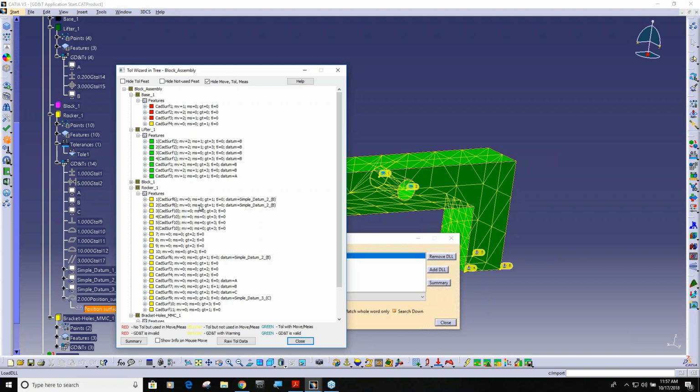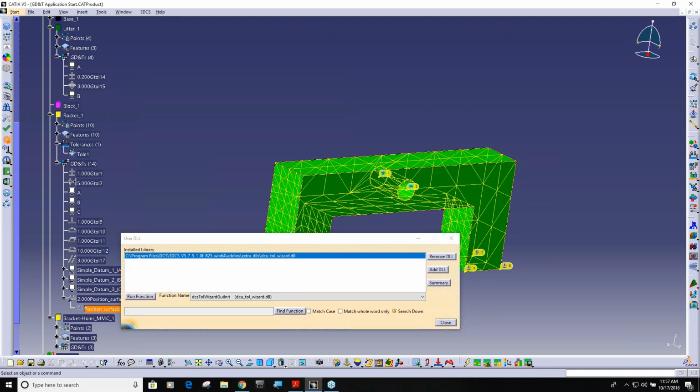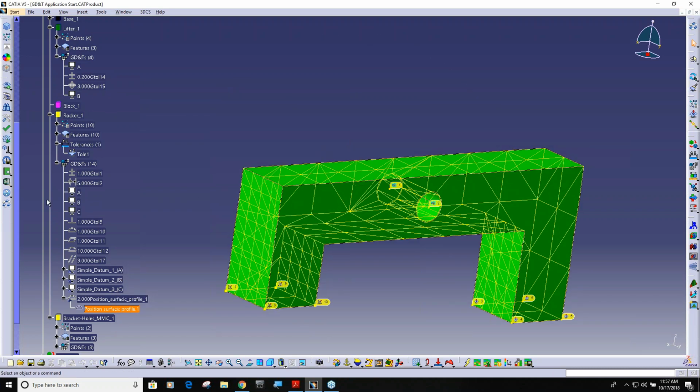Can you just review real quick opening a part with PMI or importing the part GD&T? Remember that since we're in CATIA today, the PMI or embedded CAD GD&T is called FT&A. But in Creo or NX, it's PMI, and in our previous recordings from the last session, we do show extracting the PMI from Creo or from NX.